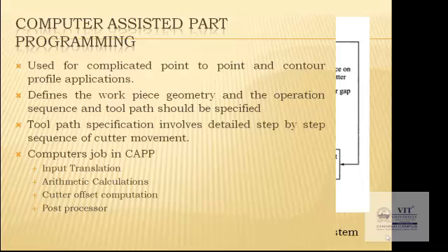In those cases, the values are set to the constraint value, that is the maximum value. This is not always possible, but in many industrial operations where you can't predict all the values, the ACC method is used. Otherwise, you can go with adaptive control with optimization.